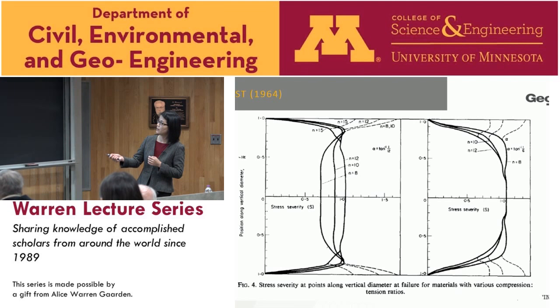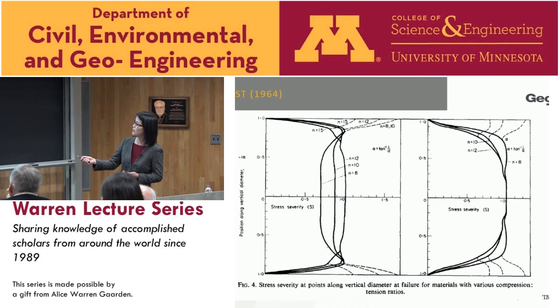He plotted the tensile stress as stress severity, in other words, how close you are to the failure envelope. So that's above 1. Now with N equal to 8, your strength ratio is decreasing. That's now below 1. In other words, in the center you will no longer fail in tension, but near the edge, the loading area, it's more possible to fail in the loading area when your N is small.